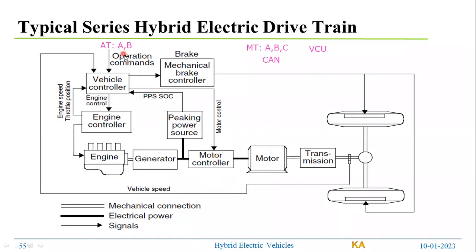And let us say the command is brake. Again there are two instructions it will send. The first instruction is that the vehicle will ask the motor to reduce the speed. So ultimately the motor controller will have to reduce the power input, thereby reducing the speed. Second, it will go to the brake controller, so that the brake controller actuates the brake actuators.